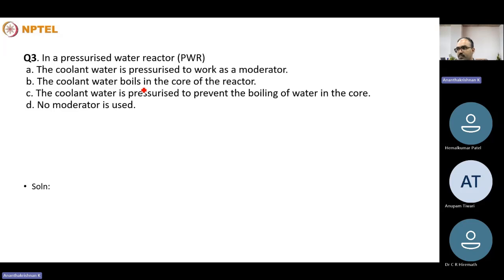But in the case of pressurized water reactor, there is a secondary circuit that will be coming in contact with the pressurized liquid. The secondary circuit uses the heat from the hot liquid to convert water into steam for the turbine. So this is a second line of defense to prevent any mishap from occurring. That is the basic difference between the pressurized and the boiling water reactors.